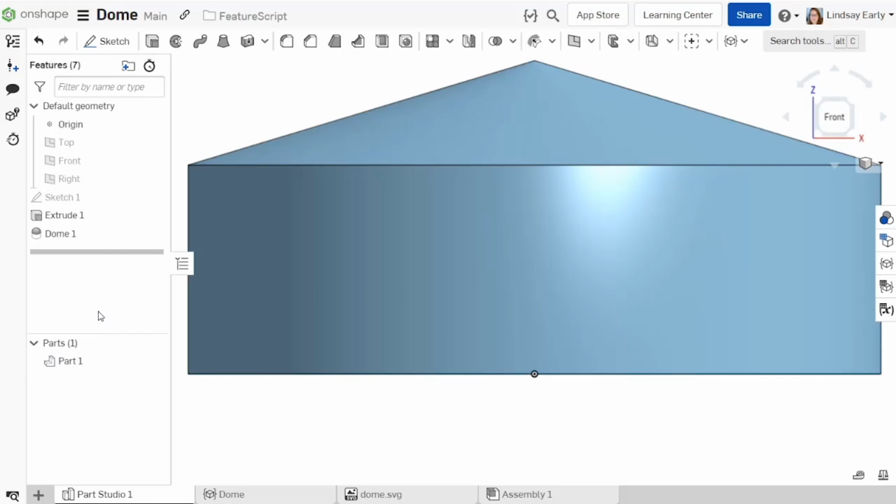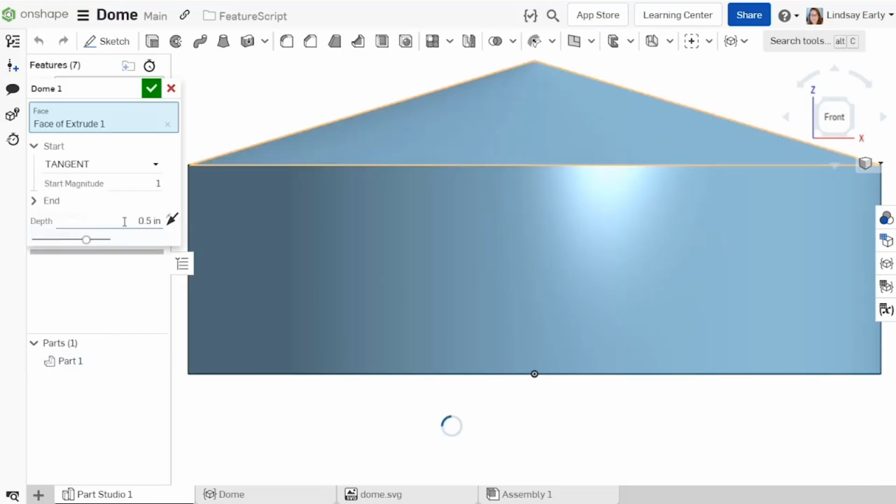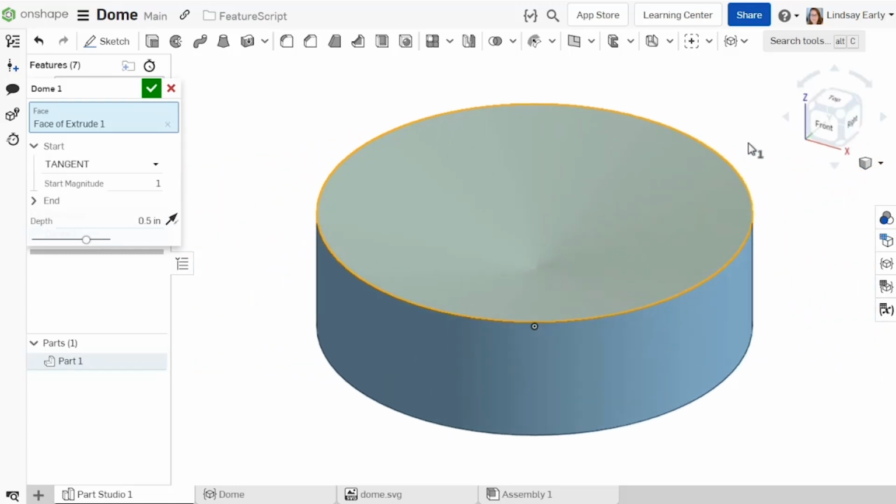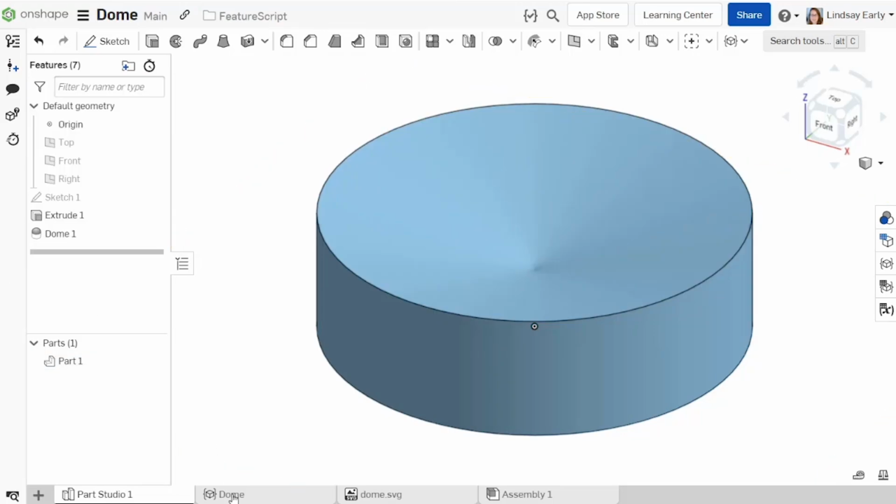In the Part Studio, the loft appropriately combines with the original part, either as a convex or concave dome. If you try to create a concave dome that is the same height as the boss, the feature errors out. Finally, add the necessary functions to develop the start and end types.